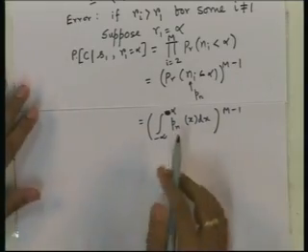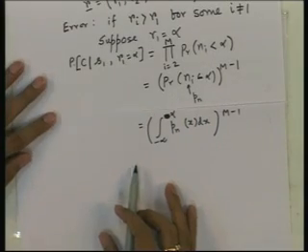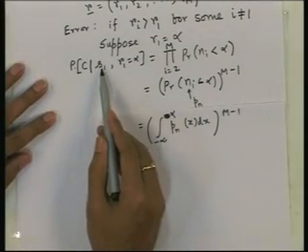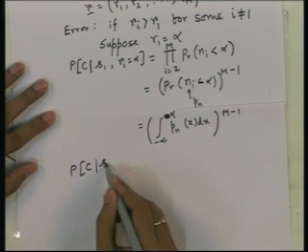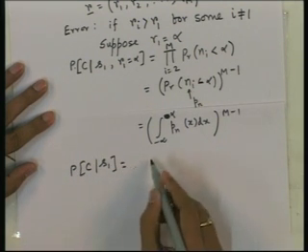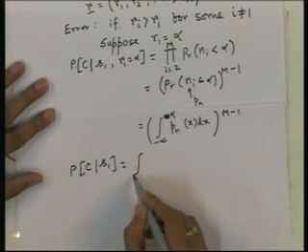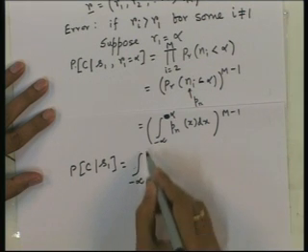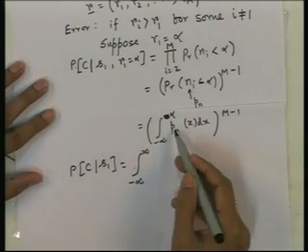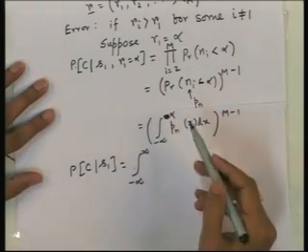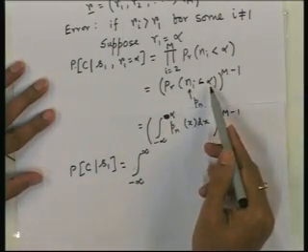Okay. Now, this alpha itself may be of different values. So, to take the average probability of error given that S1 is transmitted, that is, to compute the probability of correct detection given S1 is transmitted, we now have to average over all values of alpha also. That is, we have to take alpha from minus infinity to infinity, then take the density of N1 being such that R1 is equal to alpha.